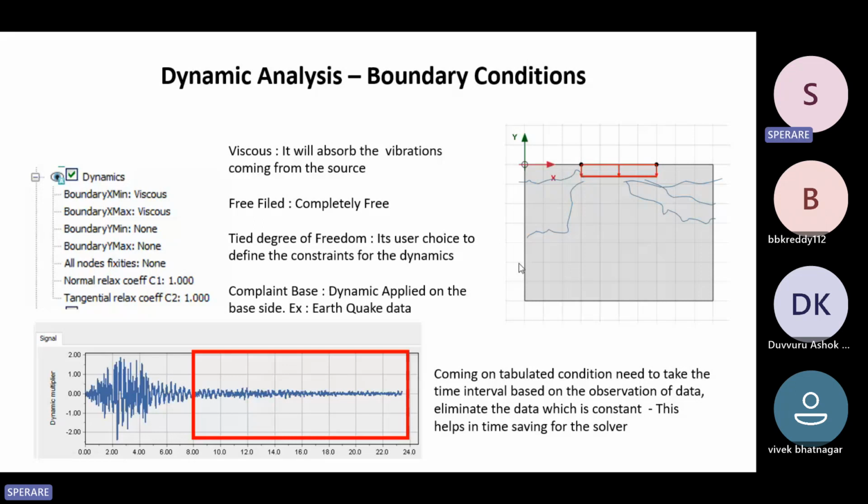But just to avoid complexity issues, wherever the region that we apply, suppose this region is 5 meters, then we go 5 times, as you have seen in the axisymmetric model for the first time. The same thing there, it's like 3 to 5 times, as I told. If it is a static analysis, that is plastic calculations, you go with 3 times. But if it is a dynamic analysis, it is a must that you go for 5 times.